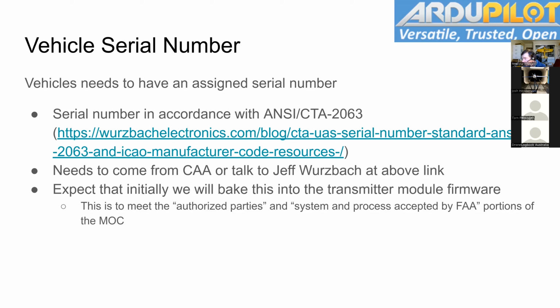So you could enable both serial and CAN in parallel in your firmware, which means people could plug in on either. But the key thing is, can you plug in at all? Or are you going to have to have custom carriers? The cabling side of this, I'm just dealing with the software. You have to also think about the cabling and how exposed that cabling is to an end user unplugging something, plugging in a different module and bypassing.